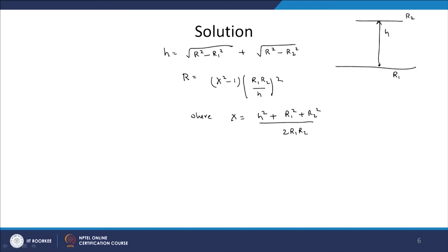So, this is how we can calculate the view factor using the inside sphere method. All we have done is fitted these two flat plates inside a sphere, calculated the radius of the sphere, and based on the formula that the view factor is equal to the area of surface 2 divided by the area of the sphere, we have easily calculated the view factor between these two parallel discs.